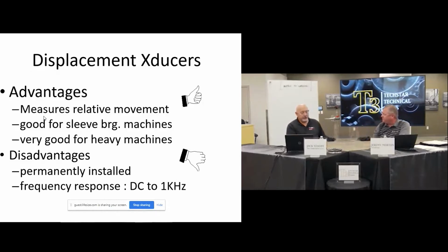They come to mind. Yeah, for probably 98% of machines you're in the range, but you may have prox probes on a gas turbine that's turning 20,000 RPM. Okay, so higher speed. Yeah, sleeve bearing application. By doing that, you're able to get about 3 times turning speed frequency to analyze.